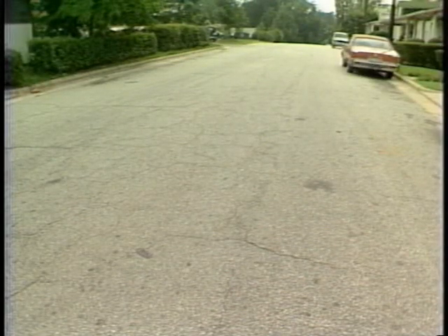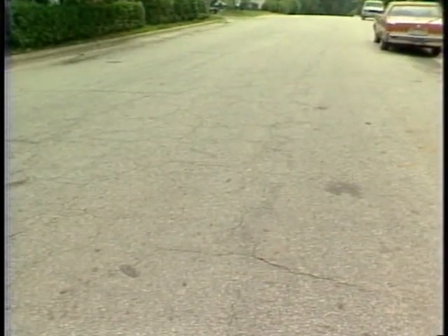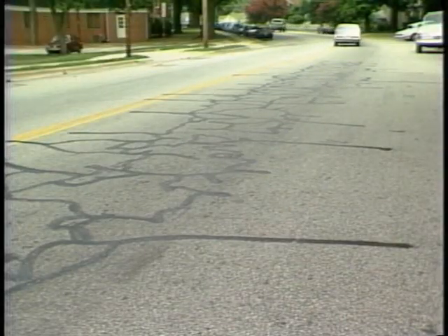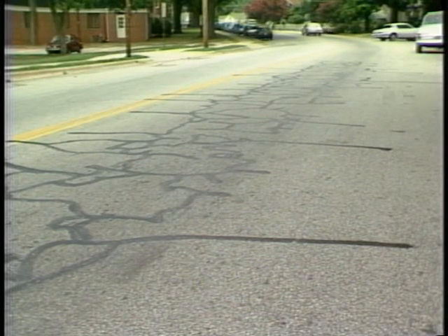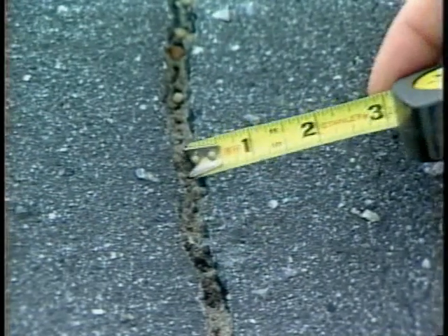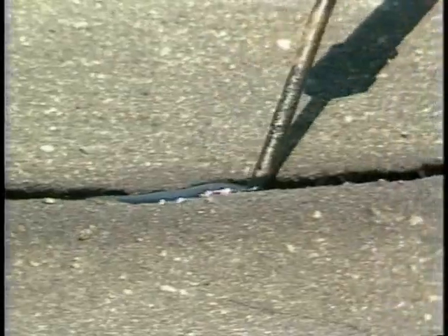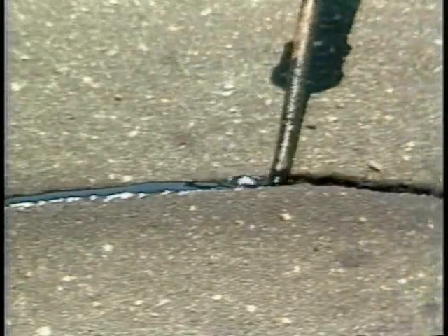Some pavement sections may have extensive block cracking with small blocks of 2 to 10 square feet formed. Alternate maintenance repair procedures, such as chip seals or overlays, need to be considered. For these conditions, crack sealing would be too time-consuming and expensive to be cost-effective. The preferred time of year for crack sealing is the winter, when cracks are their widest. However, rubberized asphalt sealants make year-round crack sealing possible.